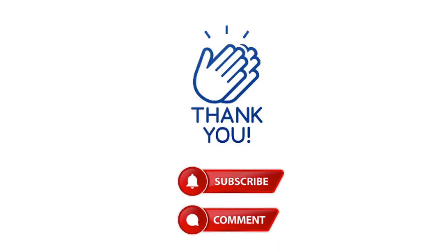Thus, we find that for all the 5 zones, there is a very good correspondence, a matching level of, say, more than 95% between the ETABS results and the hand calculation values using CalcPad. Thus, we find that ETABS can be efficiently used for obtaining the distribution of stresses, the distribution of deformations, and also in obtaining the design moments Mx and My for the structural design of the footing.